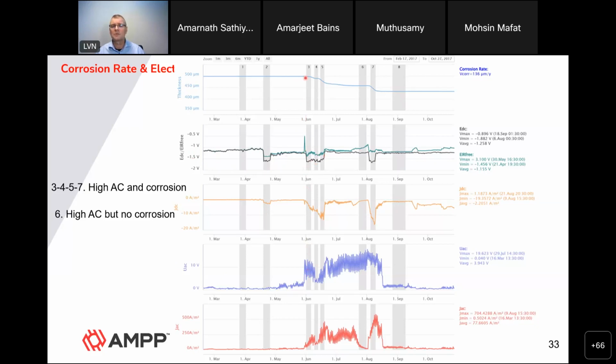We can see that corrosion starts coming to the probe, and therefore expected at the coating defects of the pipeline, if they're small enough. We can also see that the DC current is starting to increase to more cathodic values. And if I had plotted the spread resistance, you would also be able to see that the spread resistance would decrease.